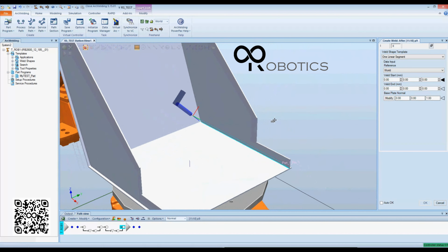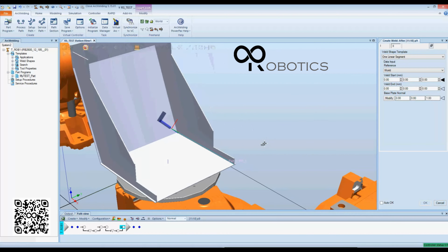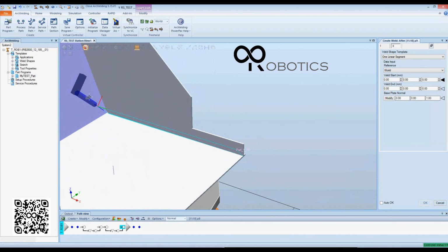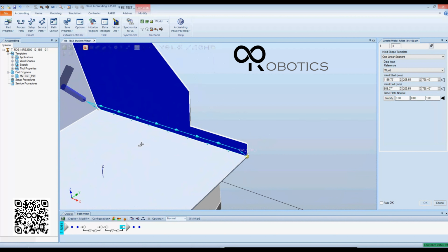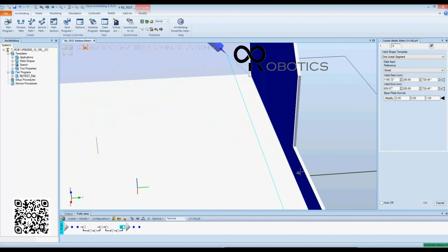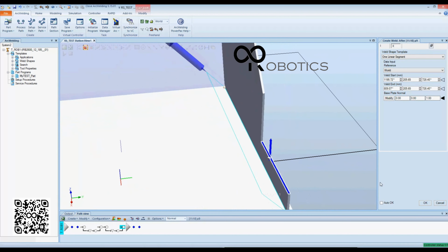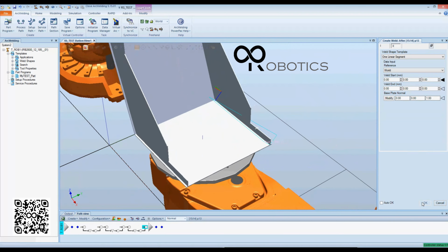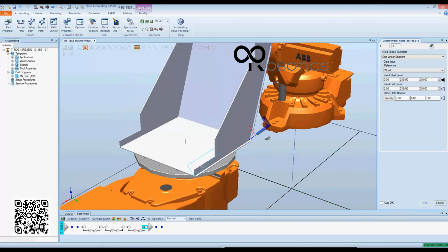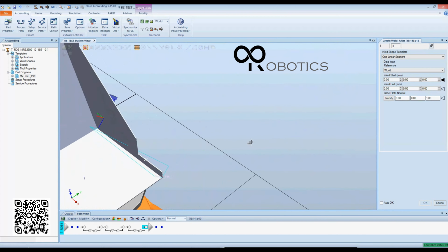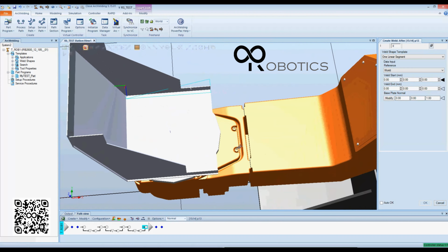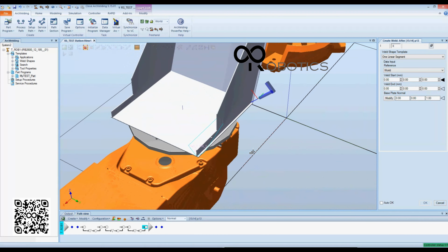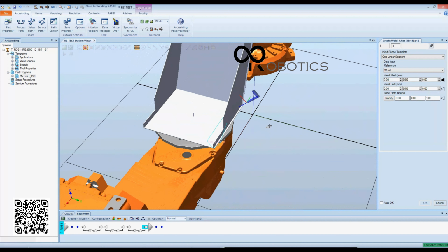So that is when you first create paths. That's the main thing about selecting a base plate. It depends upon which way the torch faces. So I'll do it one more time. I'm going to select a different base plate, and I'm going to select some surface over here, and we'll see what that looks like. So there we go. Now the path is on this side. So the base plate does affect what things reference. Get used to it, mess around with it, learn it. As you go through and do that, you'll learn different things. So it's not that big of a deal.